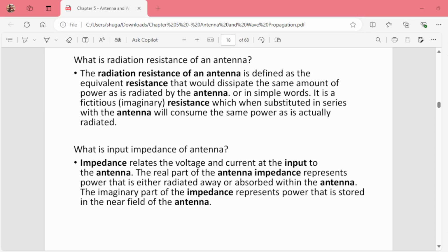If the wires or connections are not balanced, some of the music, or the signal in our case, might get reflected back, leading to a weaker and more distorted sound with a lot of noise. So radiation resistance is the part of the antenna that is responsible for sending out the signal effectively into the air, while the input impedance is the total load your transmitter has to work with when sending signals to the antenna. If the input impedance is well matched to your transmitter, more of the signal goes out cleanly. If not, you get a bad connection and some of the signal gets wasted.